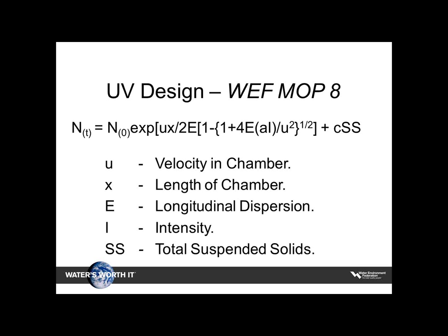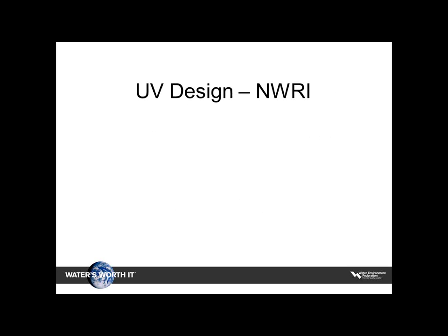So they are taking into account that the higher the suspended solids, the less likely we have effective disinfection. And again, Gary brought up a really good point early on about the dispersion or the characterization of the solids and the size of the solids itself. I don't know anybody from a regulatory standpoint, and I may not be aware of everybody, that may be requiring that, but that's certainly something I would consider in design.